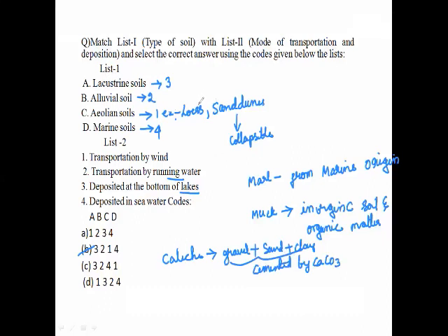And again, there is another soil you are seeing here. Then what is loess? Of course, you know that loess is an aeolian soil, a collapsible soil. It is quite less collapsible compared to the sand dunes, of course. But when you go with the definition of loess, loess is a collapsible soil of uniformly graded, wind-blown silt, slightly cemented due to calcium compounds. When it is wet, it loses its cementitious property and becomes soft and compressible, as well as collapses.